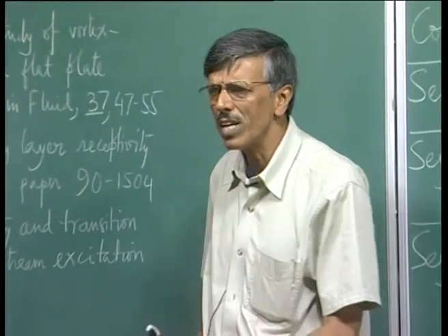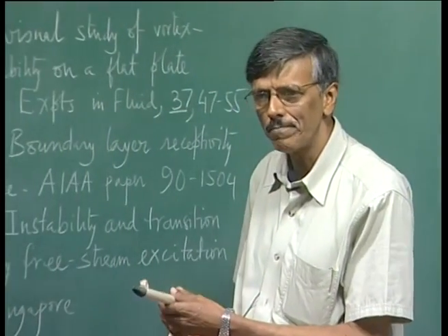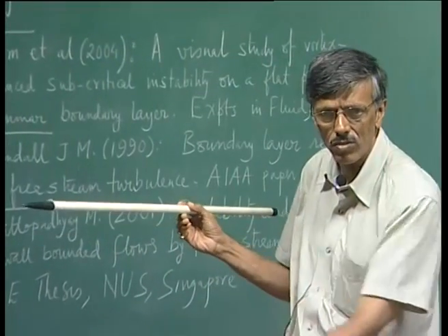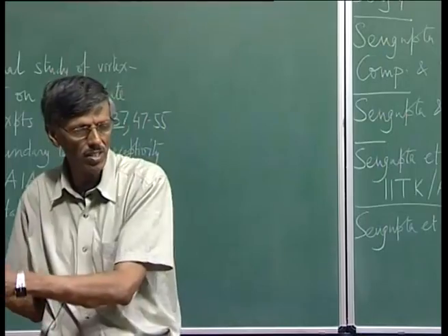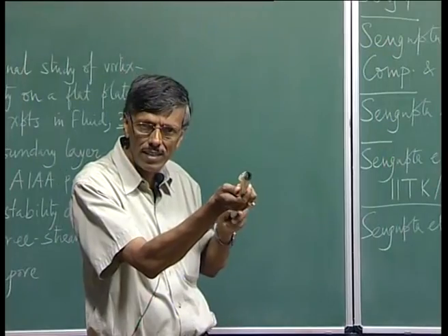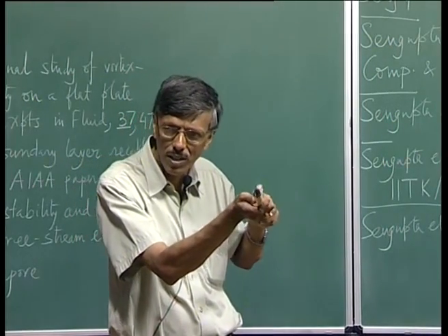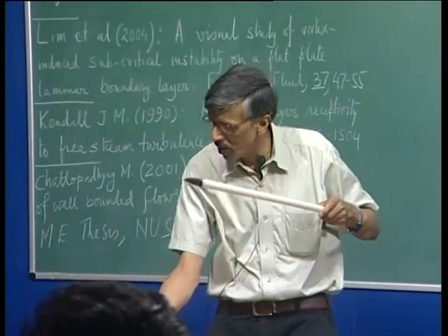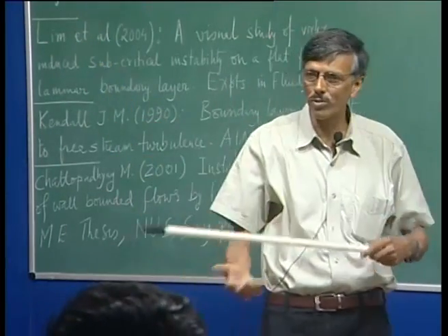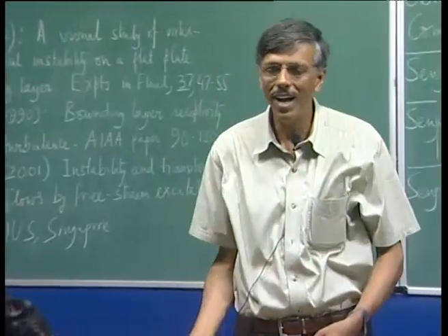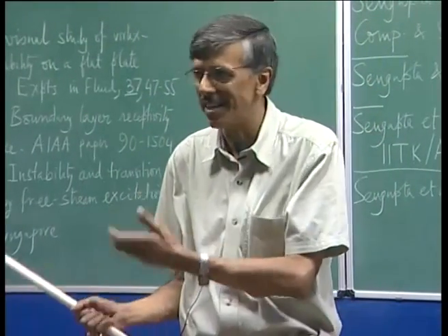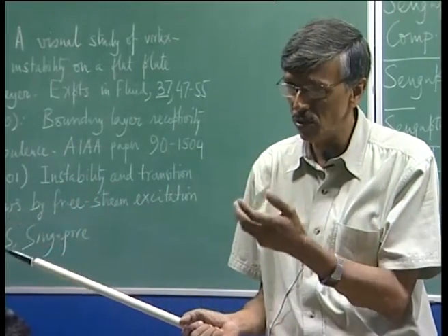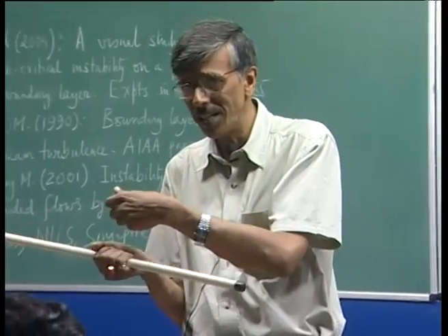Now, come to think of what the flow is doing. If this cylinder is going like this, and consider this is a boundary layer in this direction. Now, if I rotate it like this in a counterclockwise manner, then what does it do? What is the induced effect? It will try to scour out the boundary layer. It tries to pull it up, and that is what we are seeing. I mentioned it very clearly in the last class also, that when you look at the dye, you see there are two things.